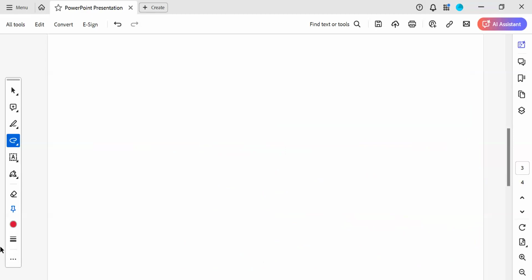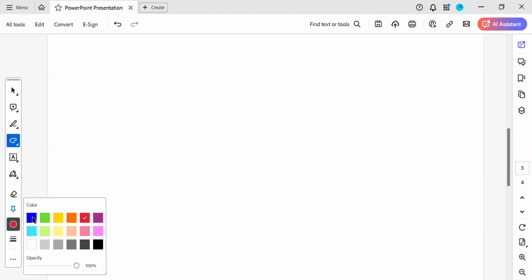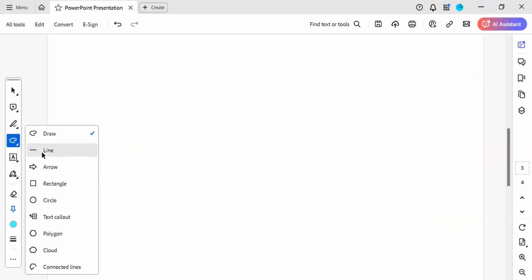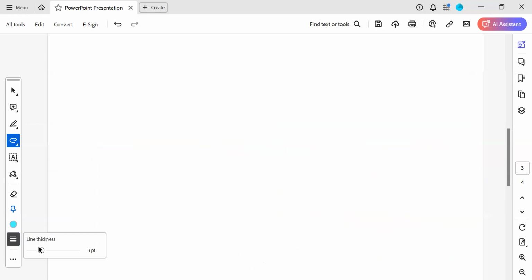Initially draw the xy line. This is the xy line. It is a horizontal line; take a scale and draw it. Above the xy line is the VP, and below the xy line is the horizontal plane.